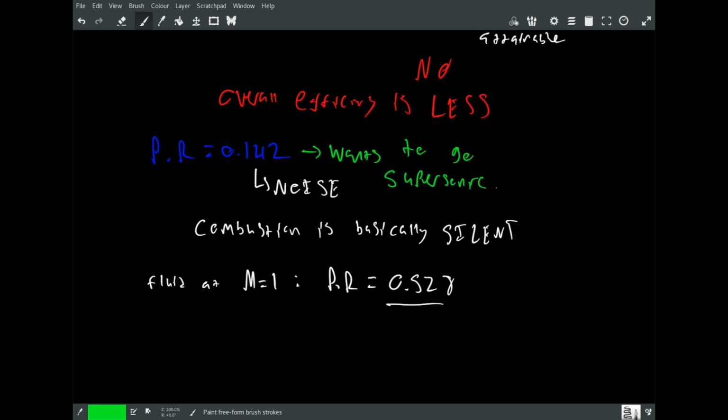So the shrouds at the exit are typically going to be more concave than anything, and you might have expansion waves going out as well, which is going to help to suck any additional combustion products. So say you have combustion products here. Well, when your fluid goes out, it's going to be probably trying to go supersonic, and you're also going to be getting some expansion waves going back into here, which is going to help to suck this additional combustion product out of the cylinder.